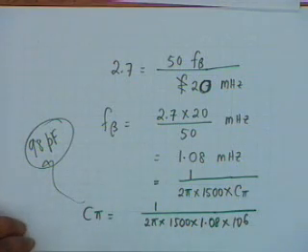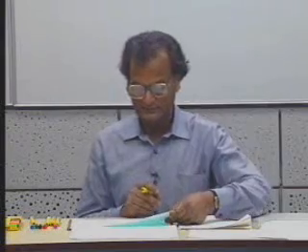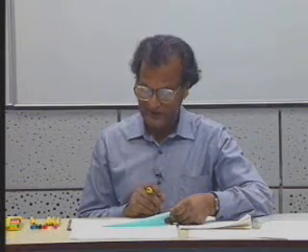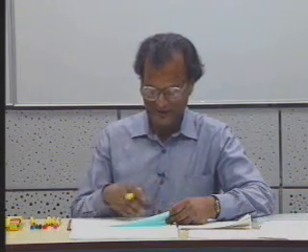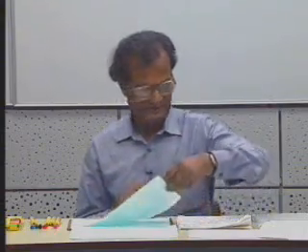That's how one finds c pi. C pi is never specified by the manufacturers. Actually it is c pi plus c mu, but c mu is of the order of a few picofarads, 2 or 3 picofarads. So we take everything as c pi. We ignore that quantity.